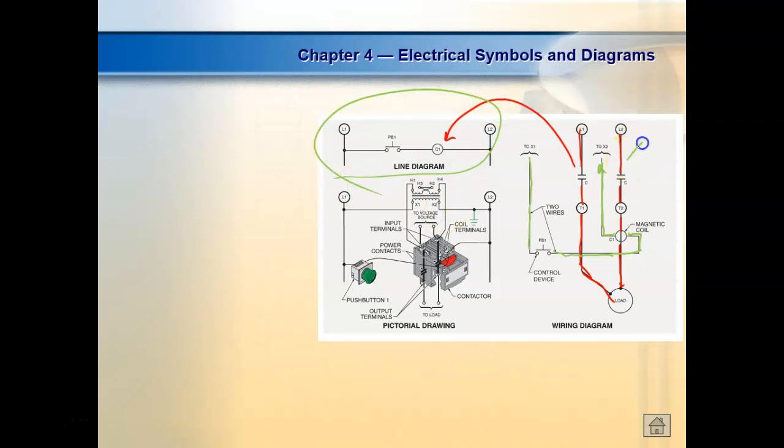So normally your power circuit is a wiring diagram. The difference between a wiring diagram and a schematic or ladder diagram is that the ladder diagram shows you the logic of the circuit, how it works. This one tries to show how things are physically oriented in relation to each other. When we get into ours and start hooking up the motor, we will see both of these. But on this side, we're going to ignore the control circuit, and we're just going to pay attention to how we need to wire the motor, right? You understand? Because they're isolated from each other anyway.